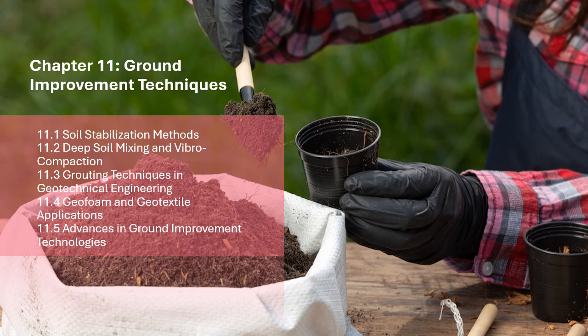1.2.1 Deep Soil Mixing, DSM. Deep soil mixing, DSM, is a ground improvement technique in which binders, usually cement, lime, or other stabilizing agents, are introduced into the soil at depth by mixing them with the native soil.